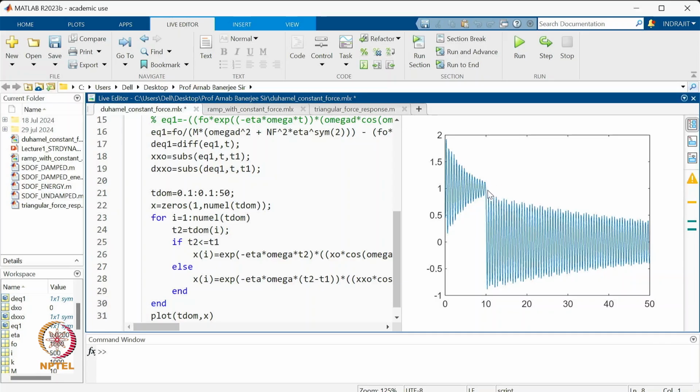So here you can see that once we leave that force, it starts oscillating over the 0.0 because it gets displaced. In that constant force problem also, it went up and took some time to settle, because the force was there. Now force is gone, so what happened? It has a displacement. The displacement amount was f0 by k primarily, because if you have damping, your displacement will be equal to the force by stiffness. Simple, because it will come back and stay at f0 by k. So it will do the same manner.